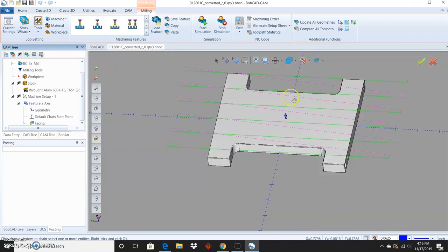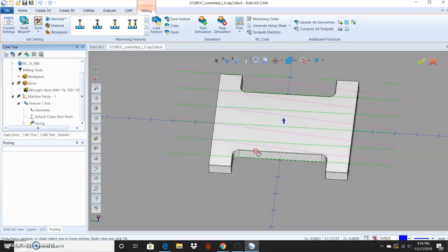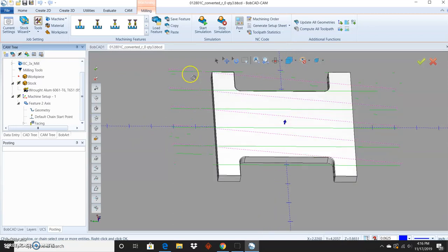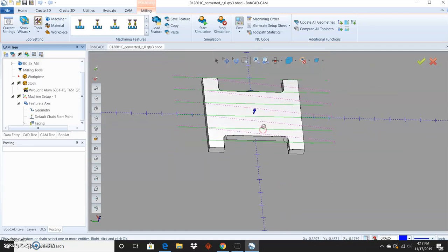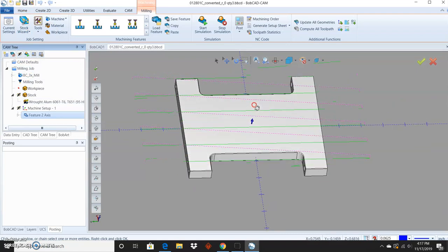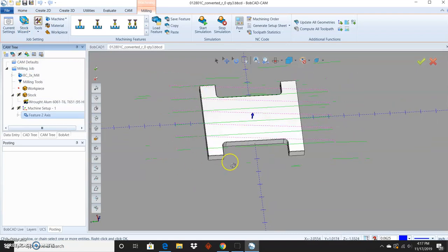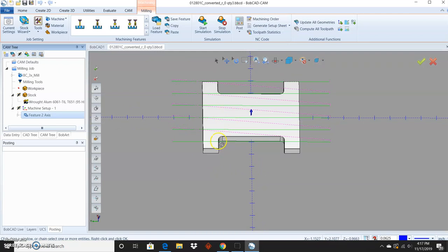Now, in this case, what I probably did was come down, touch the 50 millimeter tool to the top of the part, zero, and move down 10 thousandths. Then we face everything off. And honestly, we can use this 50 millimeter tool to rough out around the part as well. This will give us an opportunity to show you how roughing works. So we'll accept this, save it. If I wanted some other 2D geometry to be facing for whatever reason, that will be covered later. But for the most part, in a part like this, we can just select that top face and let it go to work.